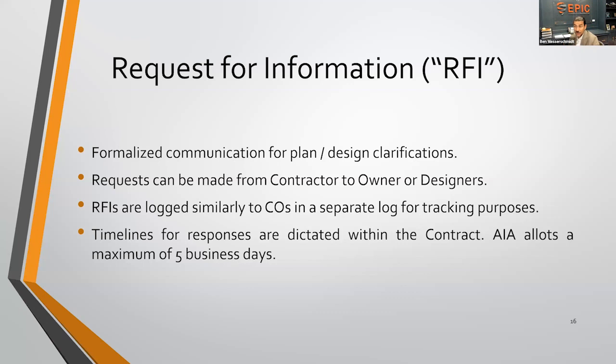RFIs are going to be logged similarly to change orders in a separate log for tracking purposes. And the timeline for responses is going to be dictated within the contract. AIA allots a maximum of 5 business days, so a week, for those reviews to be done. And there might also be some time-sensitive items independent of that time frame that may impact critical path performance from the contractor.